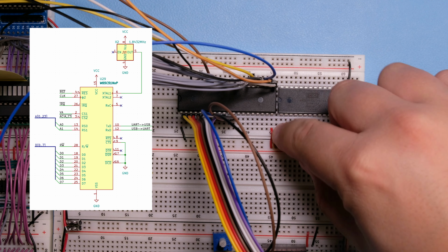And on pin 21 is IRQ, and so I have to change this. I have to add a diode. There we go, and then this can connect to the IRQ line. I think it's a bit tight here, so let me actually move this. Now reset is on pin 34 of the VIA and on pin 4 in the ACIA.